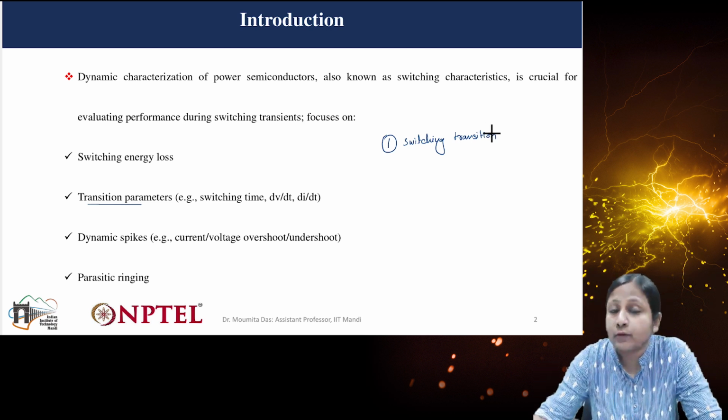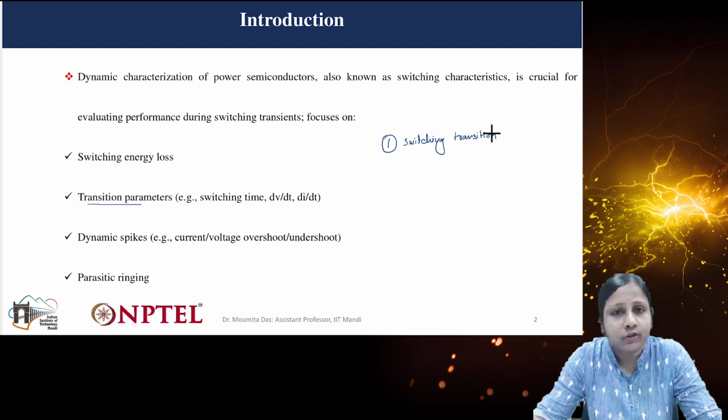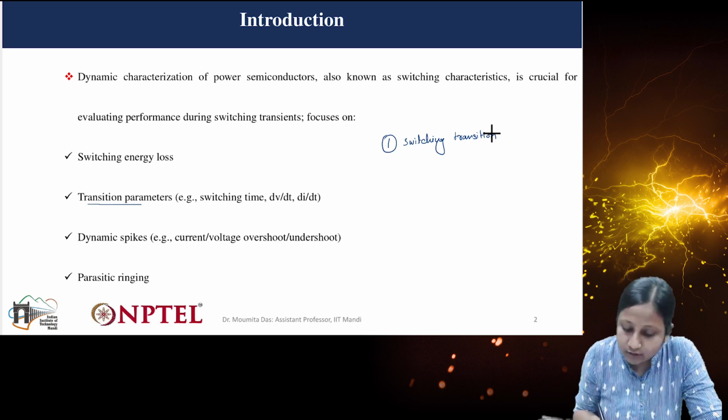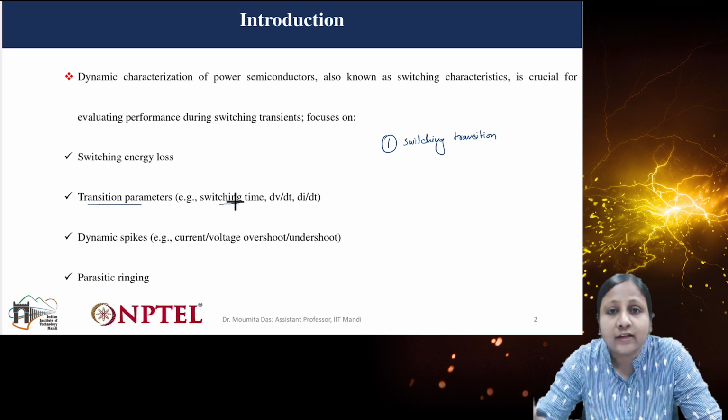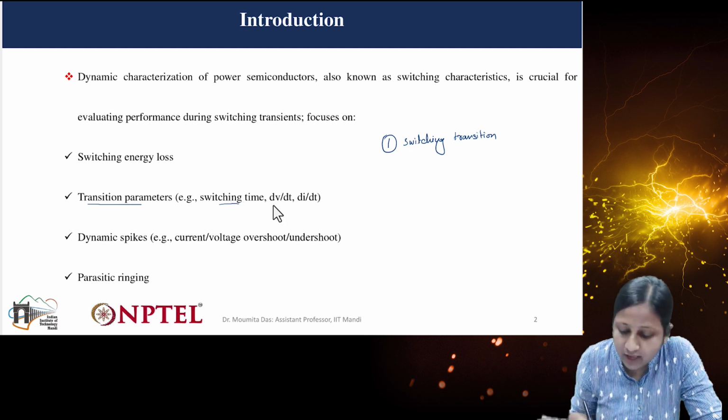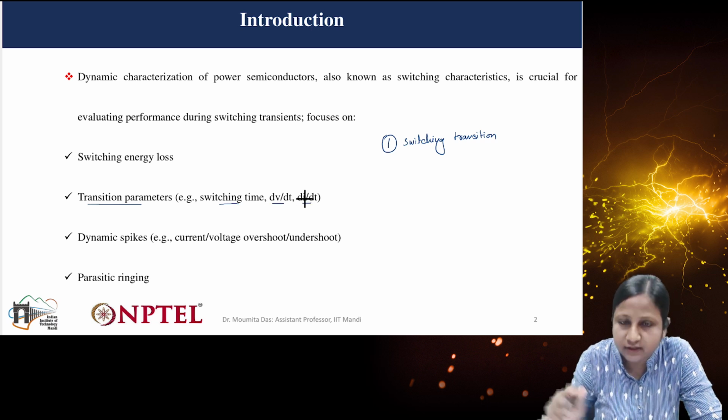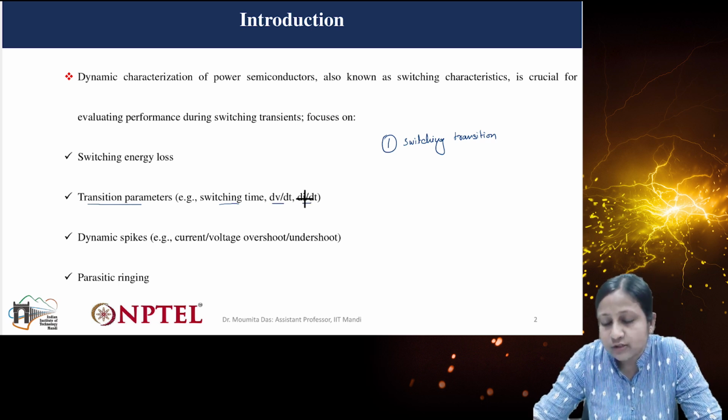So you know about switching transition. What components come in switching transition? Switching time, so basically delay time, rise time, fall time. This comes under switching time. And dv/dt and di/dt. These components come under switching transition.